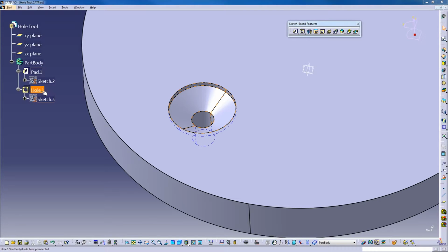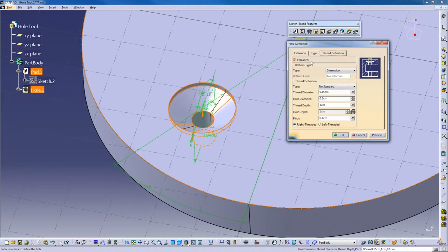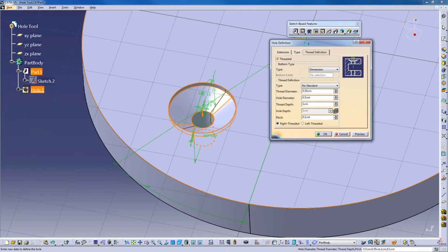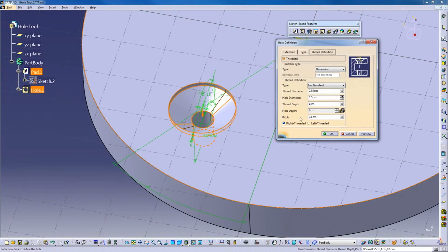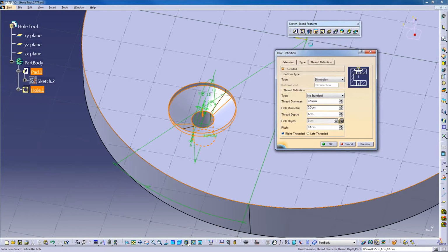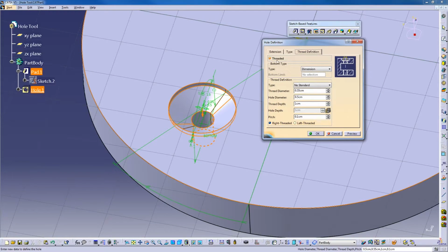So honestly, after all is said and done, the thread tap function here, there's also this tool over here where you could thread or tap any hole that maybe you did another way. Like say you made a pocket, you could tap it. Because of the things that you'd have to have in order to take advantage of this, like a tool changing CNC machine with tap ability in it and all that, most of the time I just opt for skip the threads, make the hole, and then tap it by hand after.